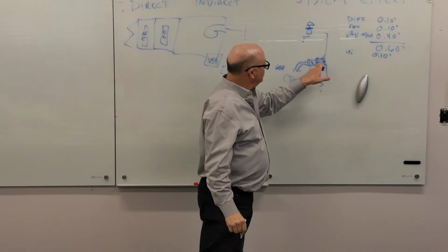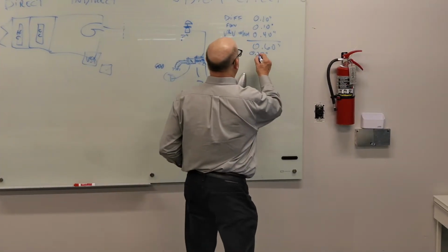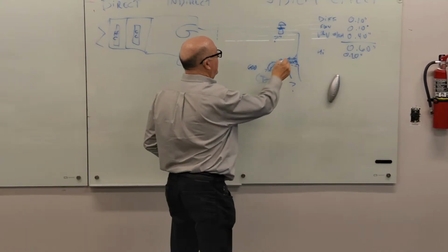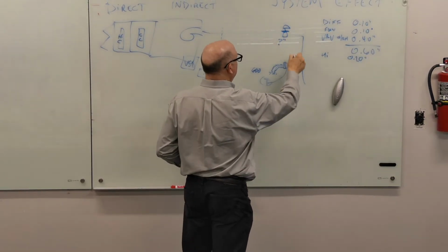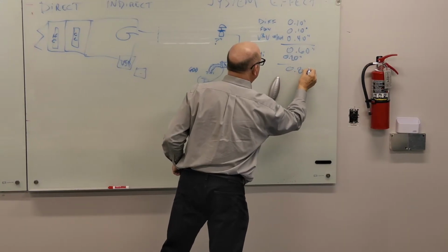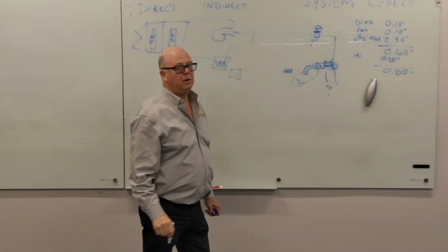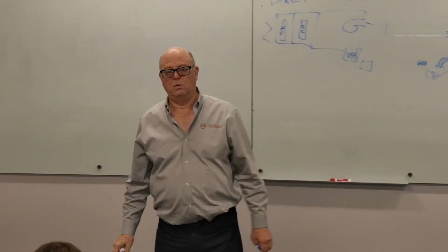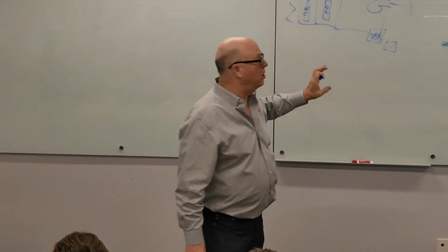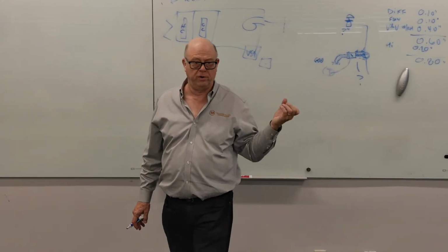But that plus the high side is probably not going to be 1/10. I'm going to call it 2/10 just for the sake of argument. And then that means that I have to have 8/10 of an inch right there. And I'll tell you that's low. I probably underestimated in here somewhere because almost always you need at least 1 inch to 1.25 inches.